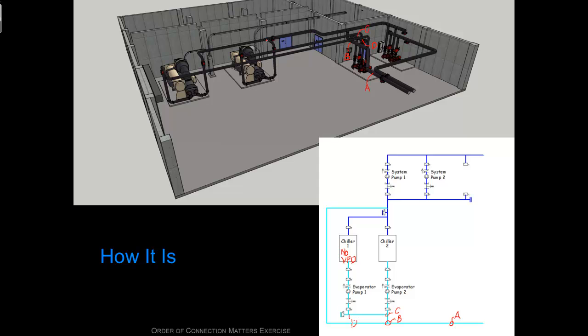So what are we at? We're at A, B, C, D, E. So this will be point E. Right here. And on this drawing, point E. And again, like all the other T's, I've got to make a decision. If I look right over, I can see that there's another T, we'll call it point F, with the flanged and capped valve, and since I'm right there, I'll probably note that. But then I'm going to go back through the chiller, because I'm sort of suspecting that's going to take me back to my pump at this point.